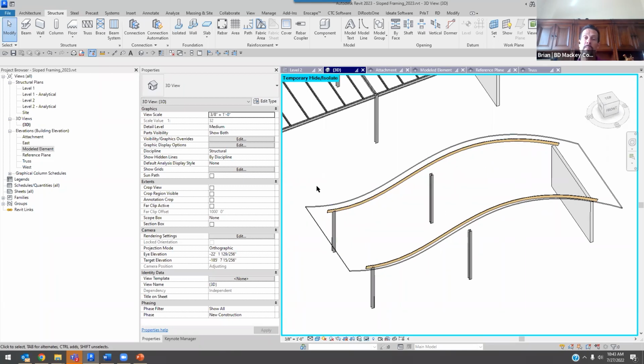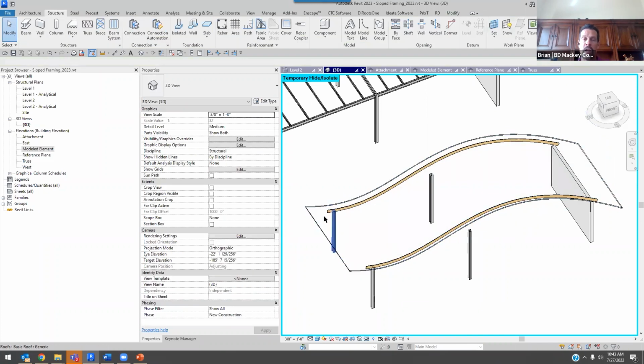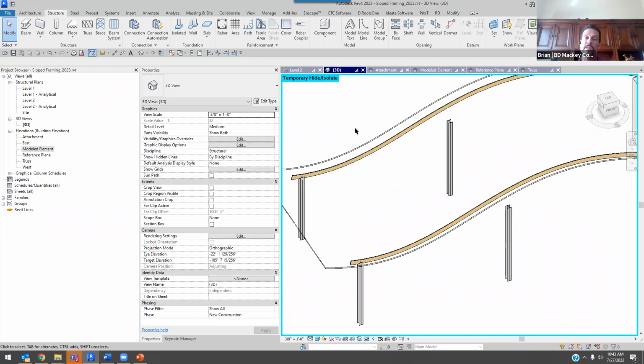How I had done this in the past, I had copied the architect's model to the clipboard, and then I did a series of basically shafts every 16 inches. I did a vertical opening or a shaft, and I copied it over every 16 inches. And then, when you do that, you can go through and pick edges of your objects for placing these elements, as long as they're on a grid line, right?